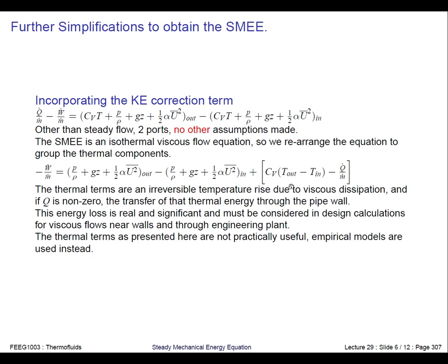So viscous flows are dissipating energy because they're viscous. You're kind of rubbing one fluid layer against another, and this term effectively generates your losses. If you did some careful measurements, you would measure that the outlet of a turbulent pipe is warmer than the inlet of a turbulent pipe. But these temperature changes are very small, and they also generate pressure changes in an incompressible fluid, and it's these pressure changes that we're actually interested in.